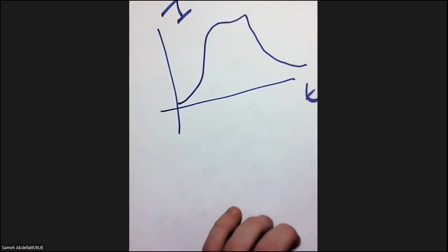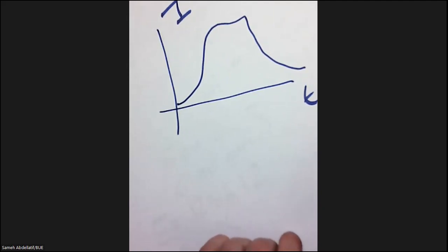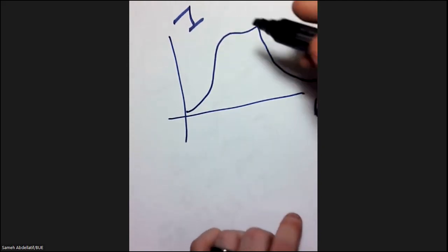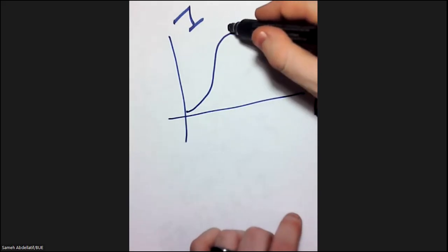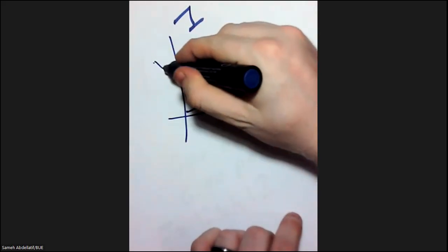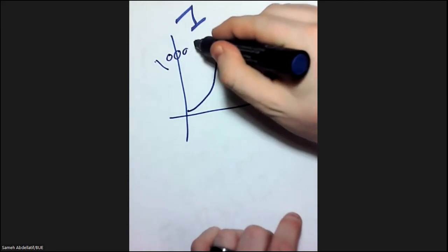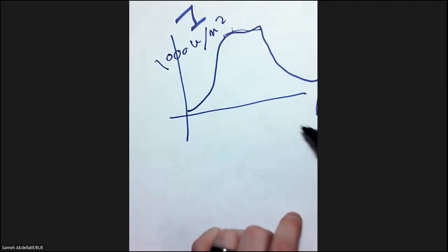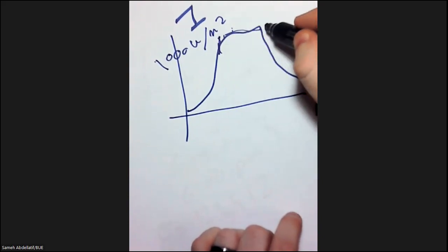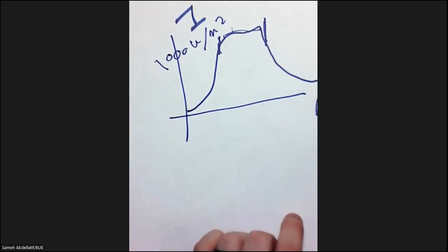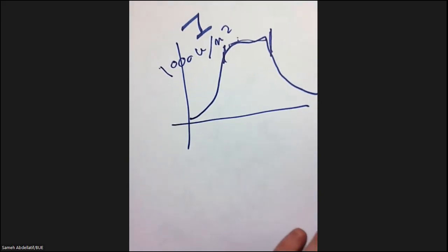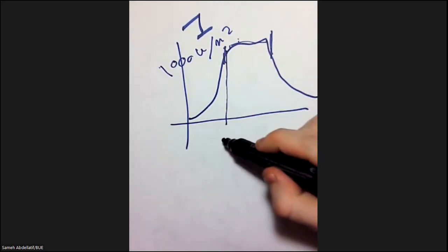So the correct answer is that you should weight this 1 watt with respect to the intensity. What I mean is, if you assume that the maximum here is 1000 watt per meter square, then during this period only you can assume a 1 watt production, because this is a one sun condition. For example, let's assume that this is from 12 to 2.